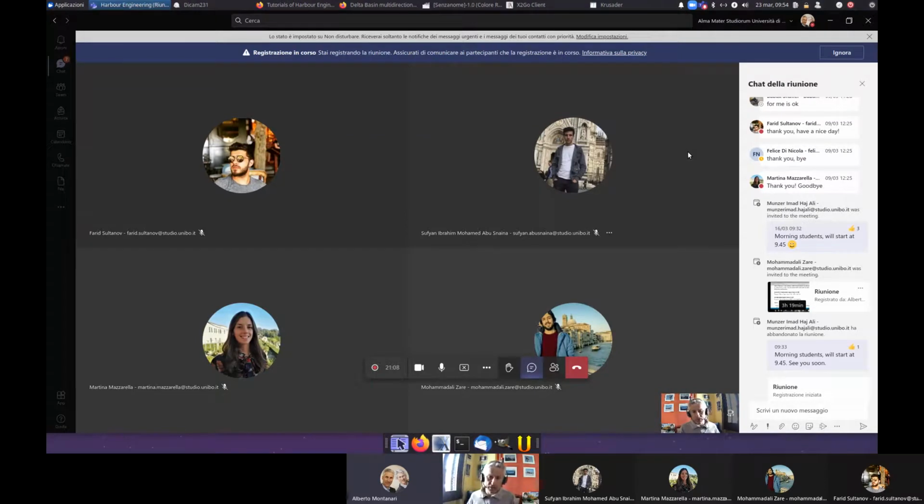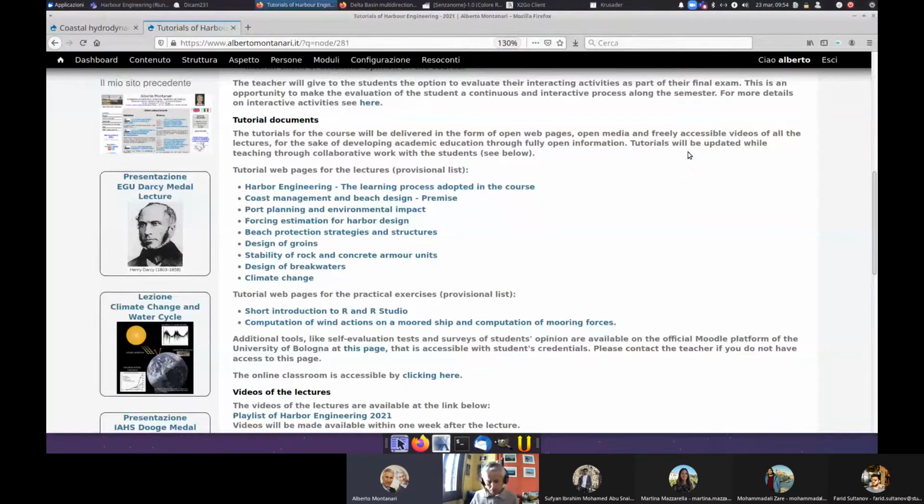So small-scale physical modeling, as I said, is an interesting alternative because it reproduces in the lab the real phenomena with a small-scale model. It's a small scale because, of course, we cannot reproduce in the lab a full Harbour at its natural scale. And this is extremely interesting. It's very demanding. These models can be set up only in very huge labs. It's very interesting because we can really emulate what we expect may happen when the Harbour is built.